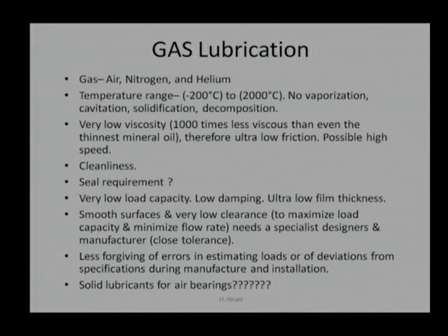What we apply is a solid lubricant coating on the surface, a 15 to 20 micron coating, that will give an extra smooth surface. Even if the two surfaces come in collision or contact, they will not wear away easily because of the solid lubricant, which, because of the junction formation, will be a low shear strength junction. That will be a good option. Maybe they mix solid lubricant with air lubricant, or apply solid lubricant on the surface and then operate on air related operation, either aerostatic or aerodynamic conditions.